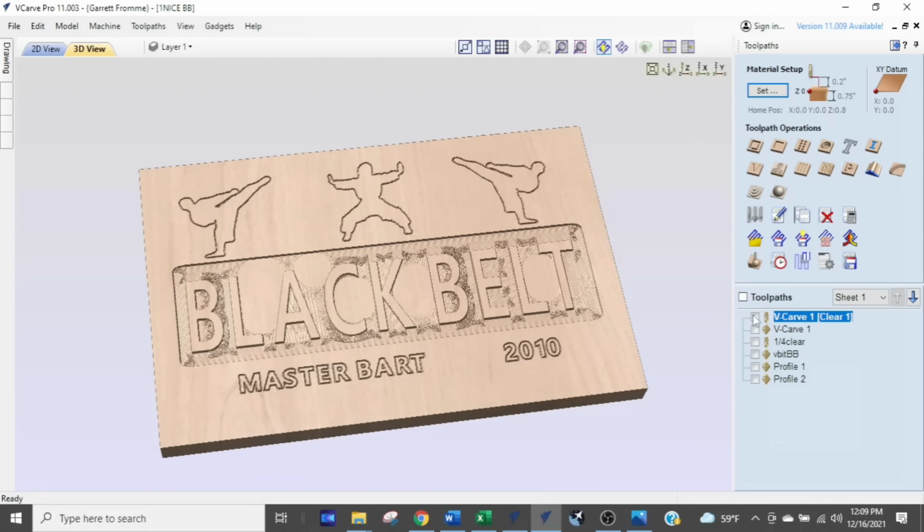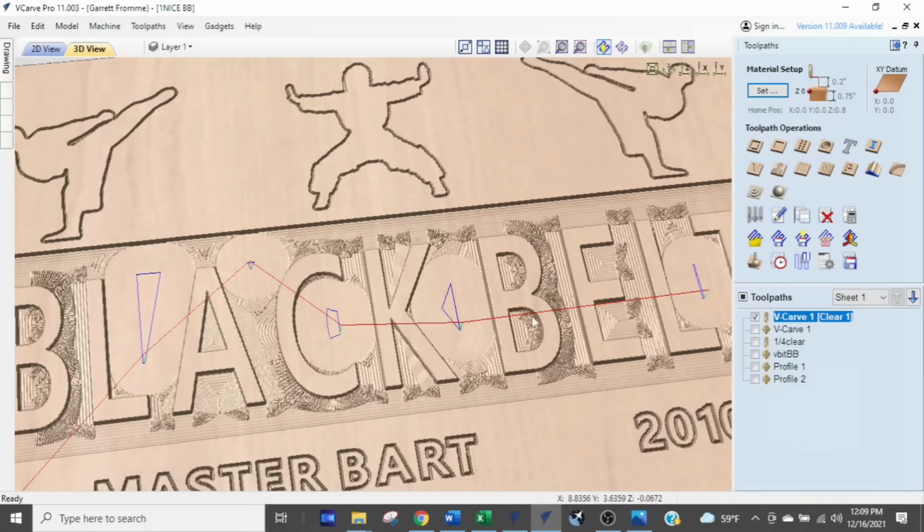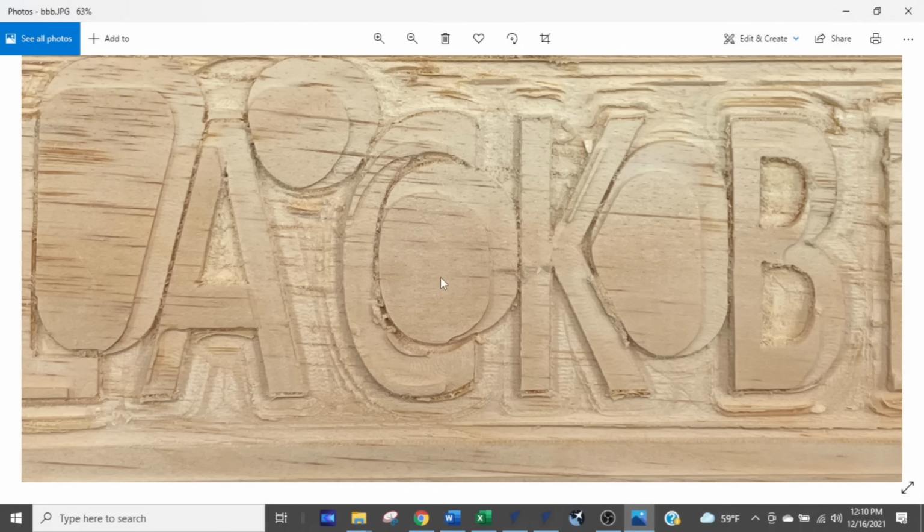So the first thing I'm going to do is really just toggle through these things to see how they look. What we're going to do by toggling is click the checkbox next to the toolpath one at a time. The very first toolpath does this little weird line, and it's a Vcarve toolpath. So it's actually taking a V-carving bit and just doing one cut, which is actually not in the picture that he actually created. So he never actually ran that toolpath.